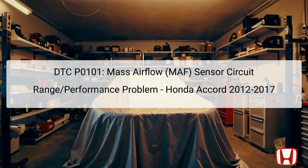The problem arises when there is a significant discrepancy between the air measurement from the MAF sensor and the data calculated from the manifold absolute pressure MAP sensor output. This can cause the PCM to detect a malfunction and trigger the DTC P0101, leading to potential delays in engine response, increased emissions, and poor fuel economy.